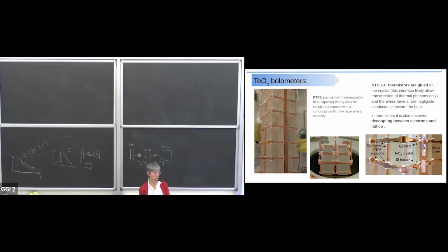No, well, it's a good insulator. Then an additional point is that when you cool down materials, they change their dimensions. You have contractions, and different materials have different contractions. So you need to also consider that.